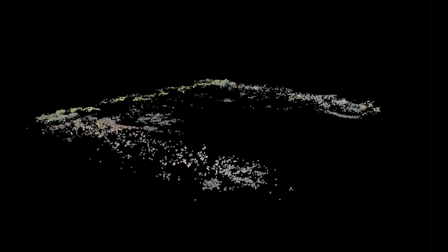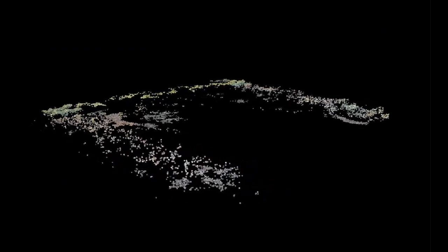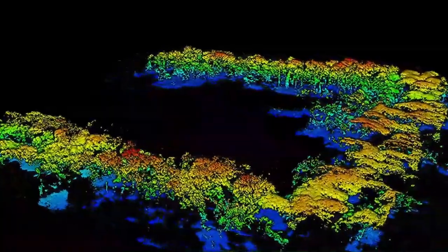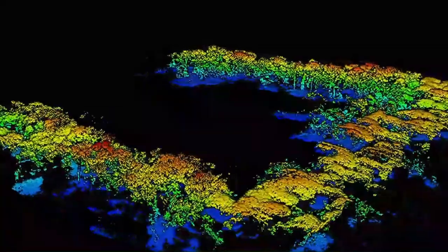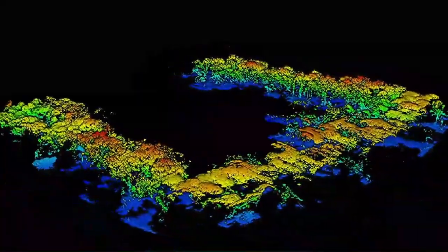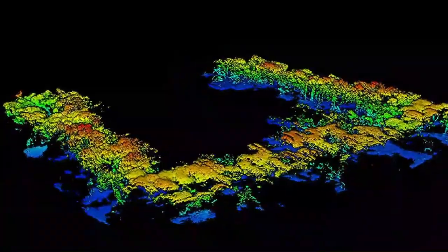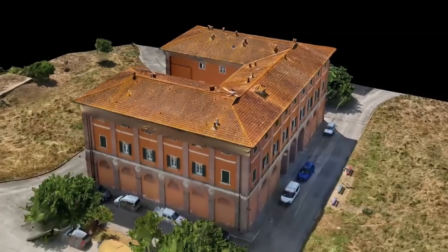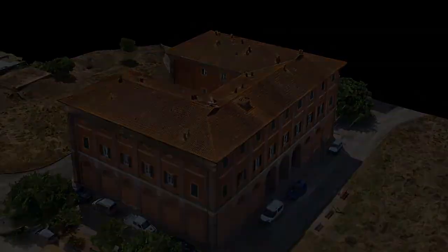Finally, we also carried out photogrammetry missions for 3D reconstruction by capturing photos and generating point clouds using the DJI Zenmuse L2 camera, with the goal of identifying specific features of a particular area of the park, features that may not be visible except from an aerial view, studying the terrain and vegetation height variations, and even creating 3D virtual reconstructions of buildings within the park, as shown in the video.